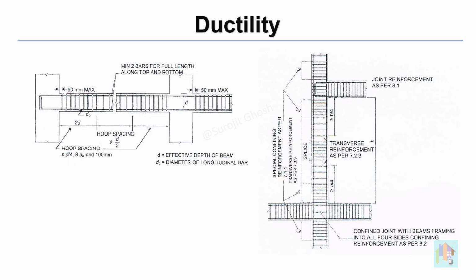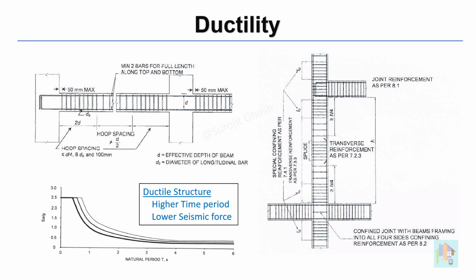What is ductility and how it affects the structural response? That is beyond today's discussion. We use few additional steps to make the joint and member more ductile by providing additional reinforcement at beam column joint of a concrete frame or extra detailing for steel member and connection. For ductile structure, energy dissipation is more. Also, it becomes soft, which increase the natural period, like a bamboo.